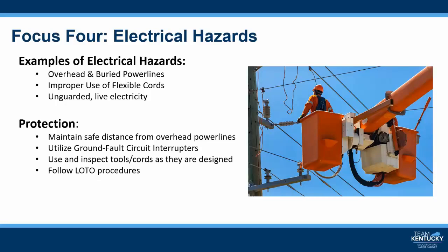Water is a great conductor of electricity, allowing current to flow more easily in wet conditions and through wet skin. Electrical burns can be arc burns, thermal contact burns, or a combination of burns. Electrical burns are among the most serious burns, and they also require immediate medical attention. They occur when an electric current flows through tissue or bone, generating heat that causes tissue damage. The body cannot dissipate the heat generated by current flowing through the resistance of the tissue.